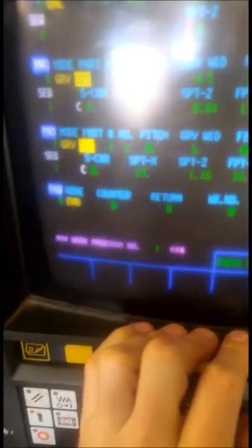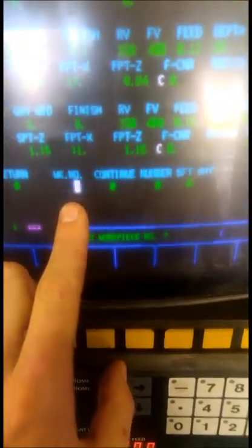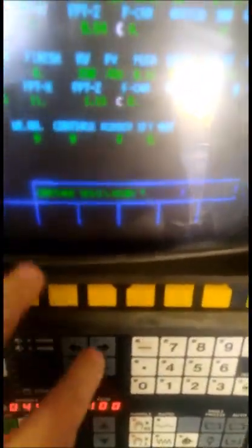The end operation is pretty handy, not so much for just single things like this, but if you're doing multiples of stuff, it's handy. So you can get it to start the parts counter. You can get it returned to the 0 position or back to home or whatever. You can set it to go to another workpiece. So if I was doing something that required 2 operations for some reason, I can get it to just switch to the next operation. Continue, so you can do this if you've got enough material hanging out to do like 10 of the same part, or if you're using a bar feeder of some sort.